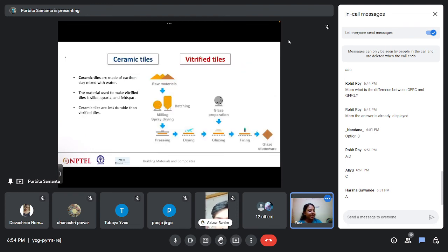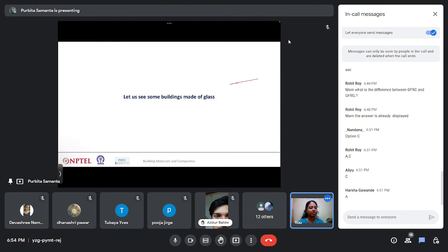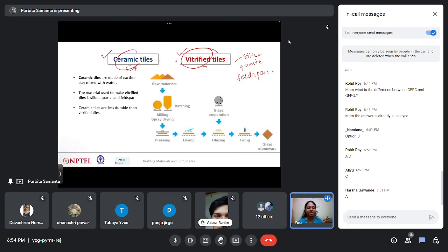Okay. So I'll just quickly explain. We have learned about ceramic tiles, we have learned about vitrified tiles, right? So what is the basic difference between ceramic tiles and vitrified tiles? Ceramic tiles are purely made of clay mixed with water. However, for vitrified tiles, we also include silica, quartz, feldspar, all these things are added, which makes the vitrified tiles, and the other one is the ceramic tile with just clay. We have seen that ceramic tiles are less durable than vitrified tiles.